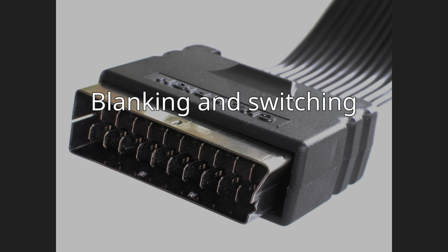0V to 0.4V means composite. 1V to 3V, nominal 1V, means RGB only. The original specification defined pin 16 as a high frequency, up to 3 MHz, signal that blanked the composite video. The RGB inputs were always active and the signal punches holes in the composite video. This could be used to overlay subtitles from an external teletext decoder. 0V to 0.4V means composite with a transparent RGB overlay. 1V to 3V, nominal 1V, RGB only.